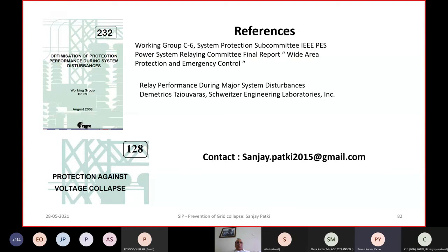No. The REF circuit will have current, but it will be below the pickup of the relay. That's why you increase the voltage setting when the fault level goes up, so that for a fault outside the protected zone, the relay should not pick up.